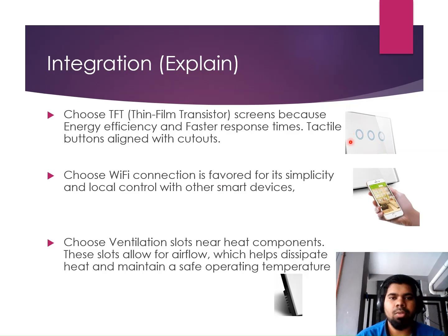For the screen, we chose a TFT screen because it is energy efficient and has a faster response, and these three tactile buttons are aligned with the cutout. Next is the connection.